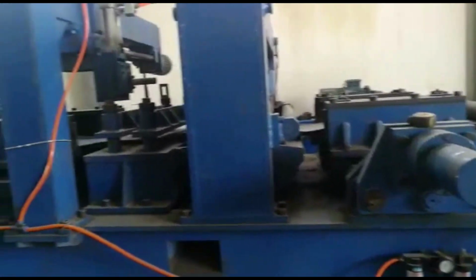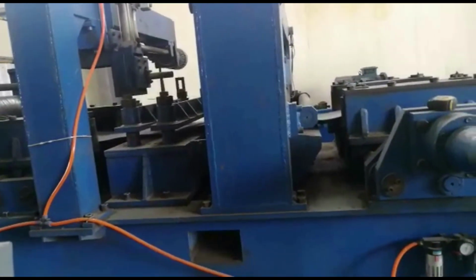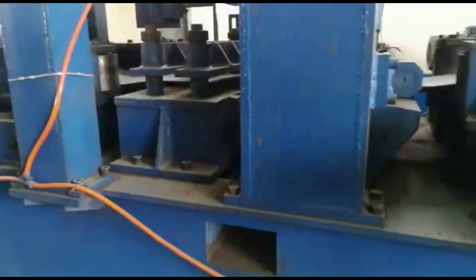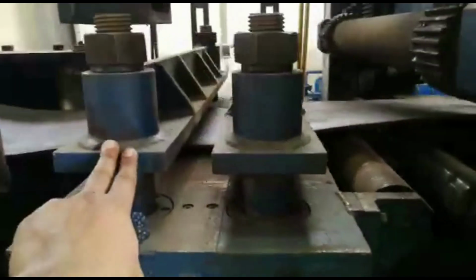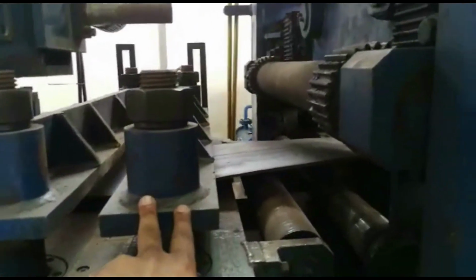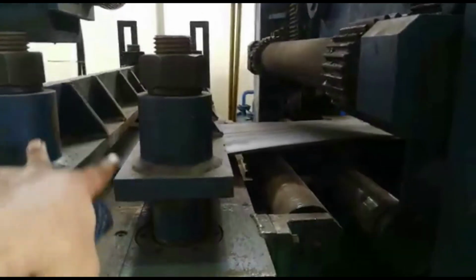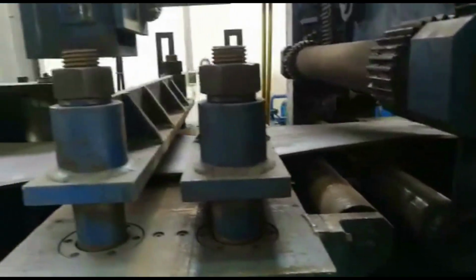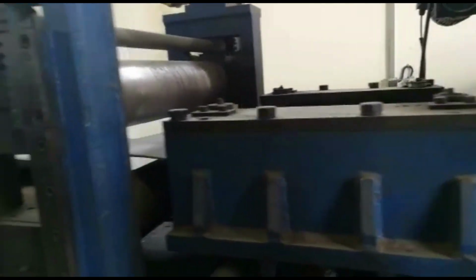From the uncoiler it passes through the uncoiler scrapper head, then to the transition table and into the cutter and butt welder machine. The cutter and butt welder machine is used to join one flatbar's end to the starting of the newly fed flatbar so that the process is continuous. The welding here is manual butt welding.